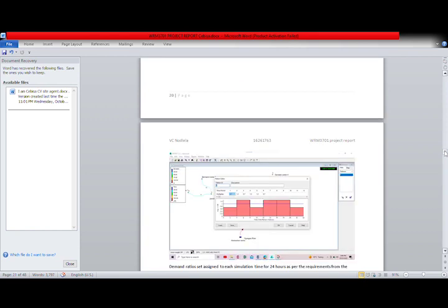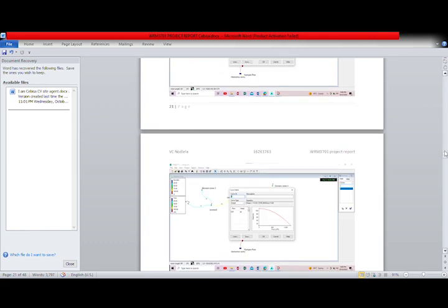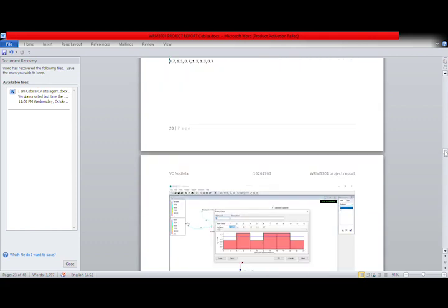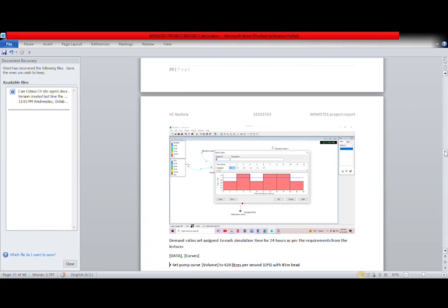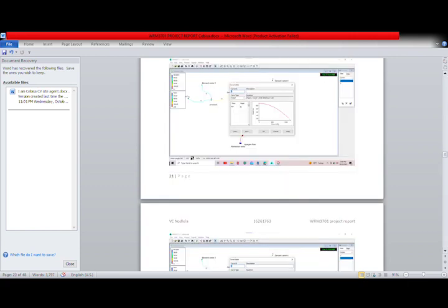And then if everything checks out, you can then go to your EPANET and run the system, as you can see here. As you can see me doing here, go to projects, then you run the analysis. And as you can see here, the run was successful. If the run is not successful, maybe because of pressure, that's when you go back and look at your dimensions for your pipes, which I experienced, and I had to increase some of the pipes.